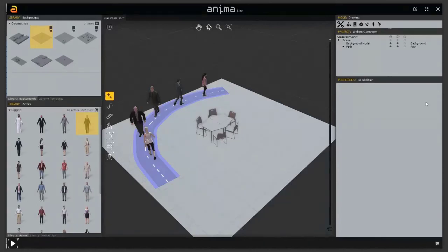Now, keep in mind, of course, that the more you change your model, the more issues you could have. Okay, but doing it this way, you should prevent having any issues. So if you delete the background model and then you create a new one in the scene, you are creating a new offset. So all the simulation elements you already have in the scene wouldn't fit. Okay, so this is very important. And this is important because of what I've explained.